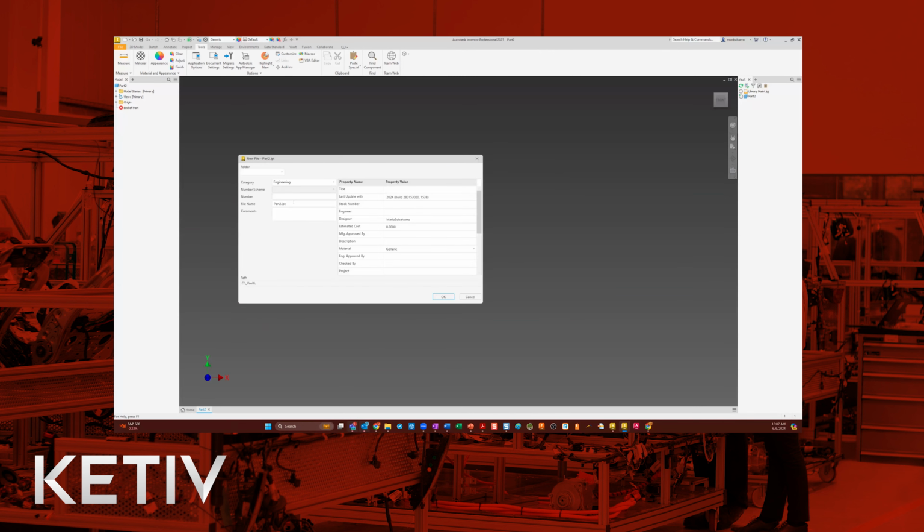And we'll come across this box here. So the example that I'm going to use, because I'm actually in a library maintenance project here for a purchased part. You have categories, file categories in Vault, and we'll take a look at that as well. So those file categories are listed here for you to select from. And based on those categories, you will have various properties that are associated.